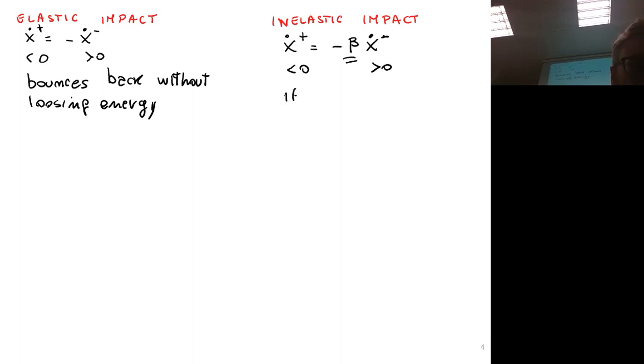You have a perfect inelastic condition if this scaling is 0. So the velocity after the impact will be 0. And this means that all the kinetic energy of the system in the impact is lost. In case of rigid contacts, we assume this is the case, for simplifying our modeling stage.